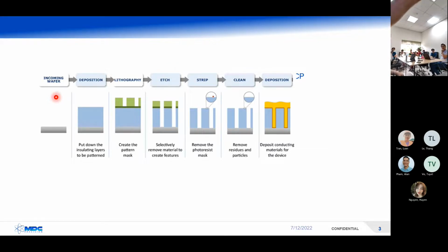So you put down the layer, just like on a cake, boom, a layer there. Then we do our masking tape. Now, how we do the masking tape is, again, it's so small you can't lay out the masking tape. So we put down a photosensitive, almost like a solvent, okay? It's like a thick solvent, and it has a photosensitive aspect to it. We put it on the wafer so it's very uniform. You want it liquid, just like if you spill water it will spread out and be kind of flat across the whole table. That's why we use a liquid, or something that can be very flat.